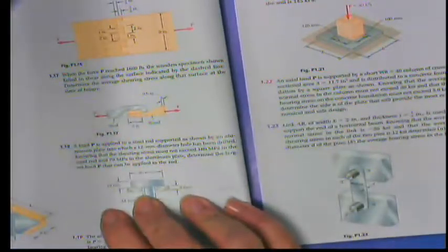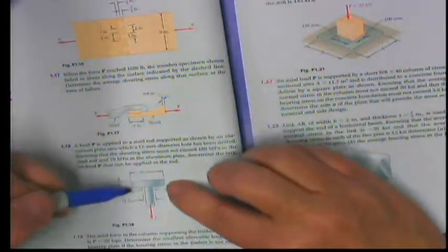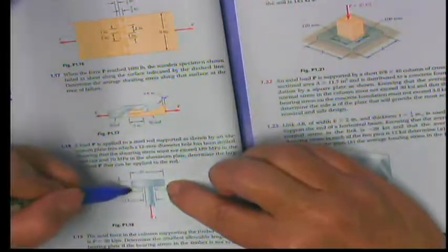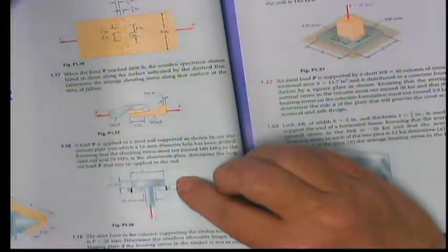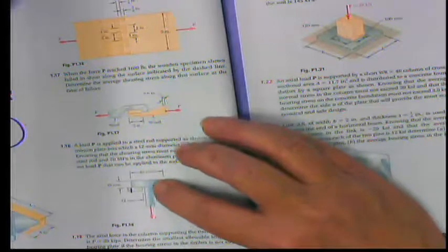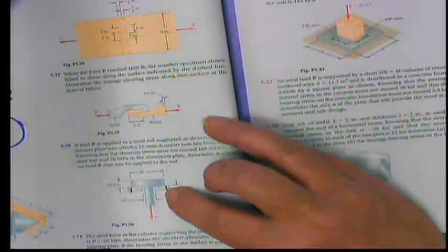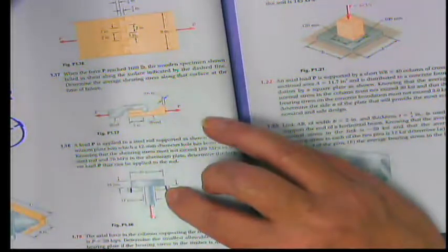So this can fail two different ways. If the aluminum plate fails, it's going to fail right here, isn't it? And if you draw that, it's going to look like a circle because this is circular. It's going to fail around that steel rod. We can't see the front?